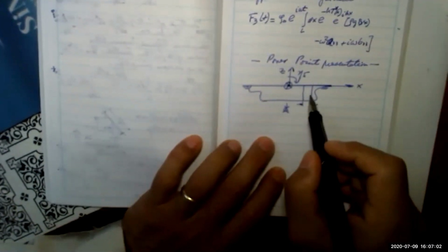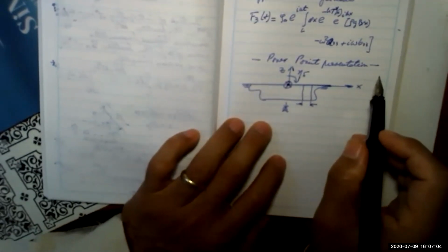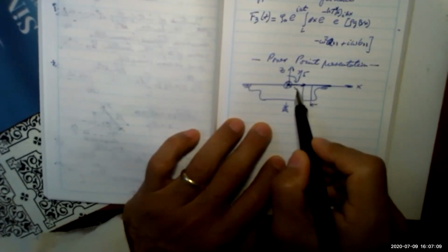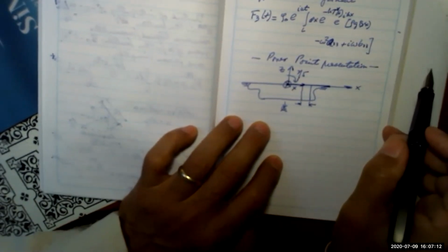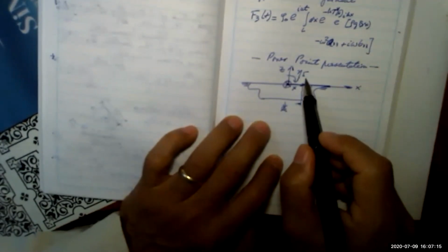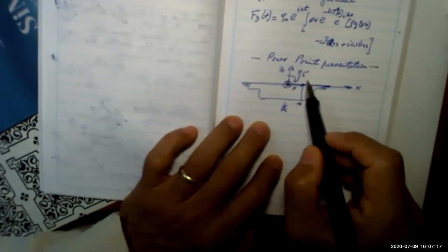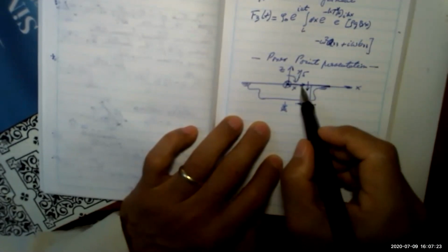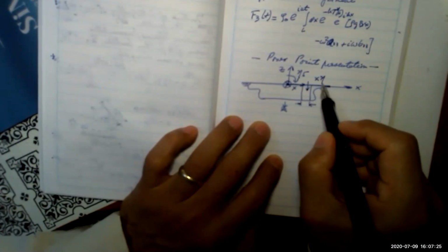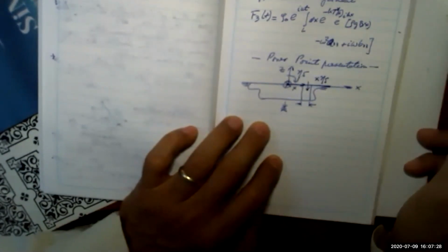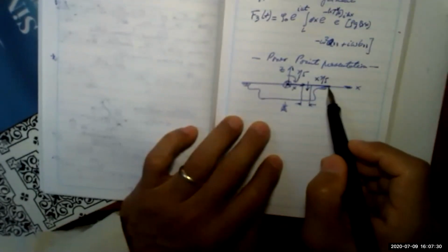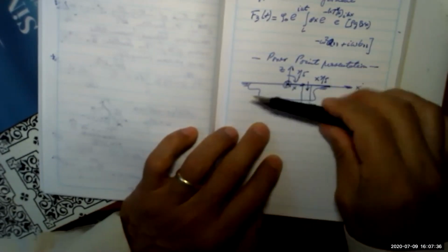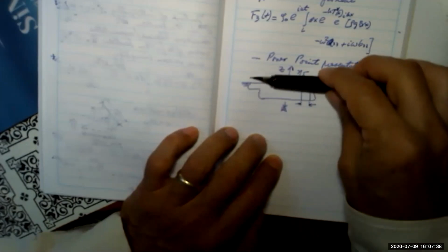Okay, so if we consider this little strip, located at the position X, and the ship moves with this rotation, that means that this strip will go down an amount equal to X eta 5. So it's very similar to having this strip moving in the vertical direction.